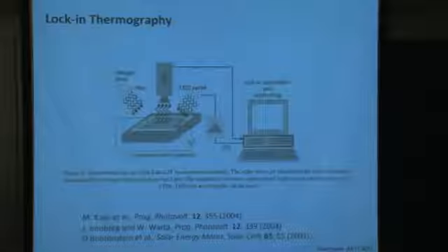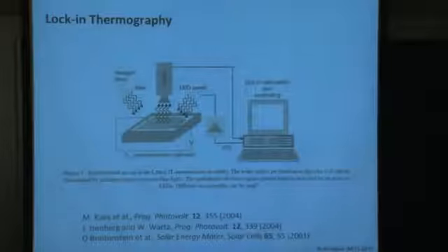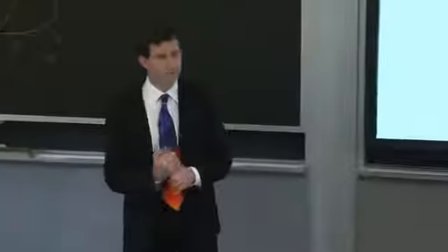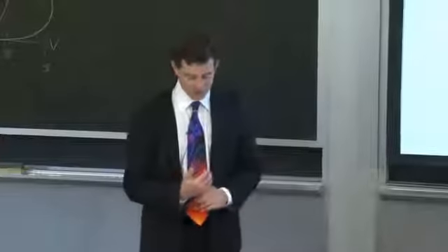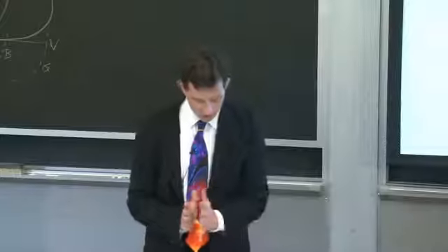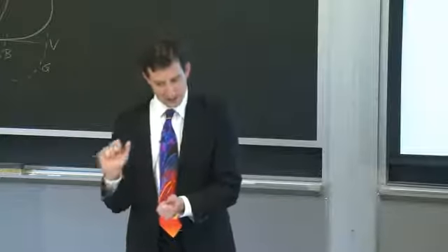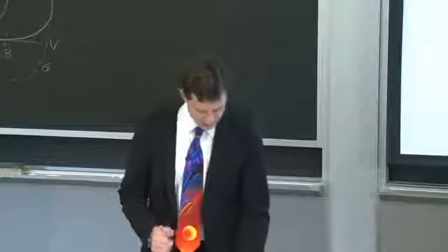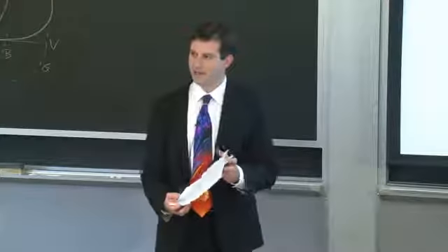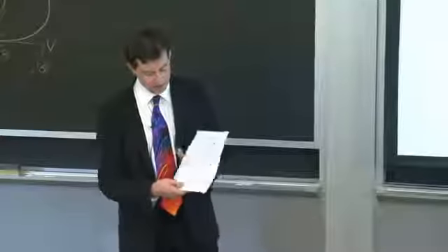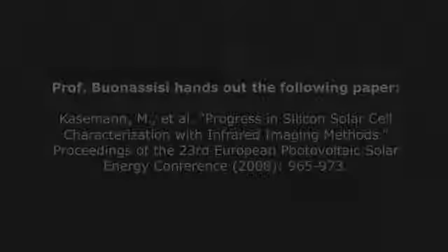And they said, well, in what other wavelengths does a solar cell emit? We know that it emits heat, right? And heat is typically in the 3 to 5 micron wavelength regime, maybe even as high as 10 microns, depending on what temperature. And we know that, as well, we can have band-to-band emission inside of a solar cell. That would emit around the band gap energy. So let's set up a camera to image the band-to-band recombination intensity, or the band-to-band illumination intensity. And that's what this paper is about.